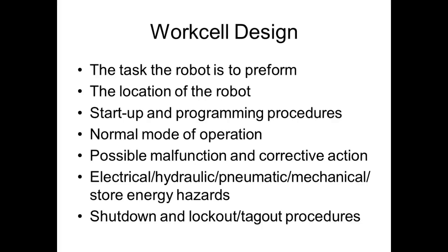Work cell design. So you understand what the work cell is? It's the space that the robot is operating within, right? So that's the cell. The design of the work cell depends on several things: of course, the task the robot will perform, the location of the robot, startup and programming procedures, normal mode operation, possible malfunctions and corrective actions, and electrical, hydraulic, pneumatic, and mechanical stored energy hazards. This gets a lot of people hurt too.